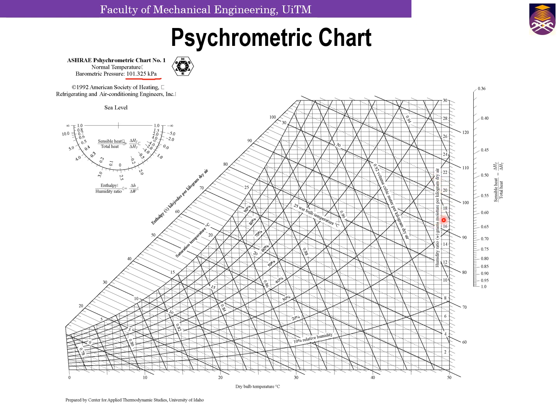We mostly use values in kilograms moisture per kilogram dry air. But in this chart, the value for humidity ratio is given as grams moisture per kilogram dry air. So if you read 22, the value is 22 grams moisture per kilogram dry air. You will need to convert this into kilogram moisture per kilogram dry air for your further calculations.